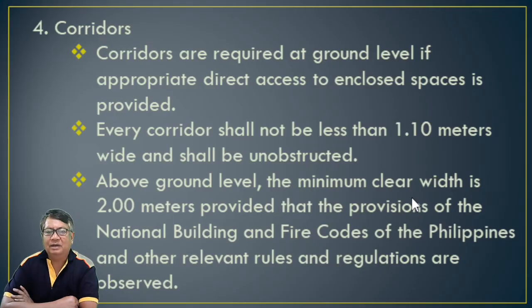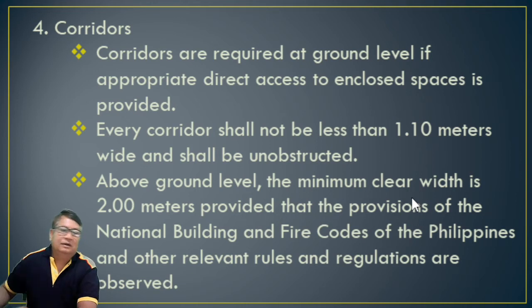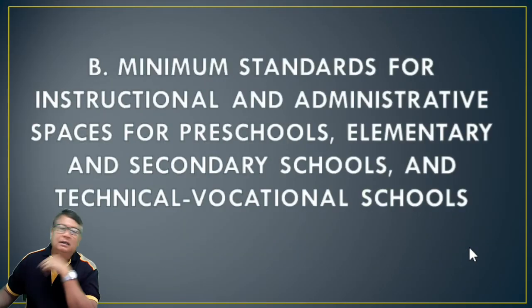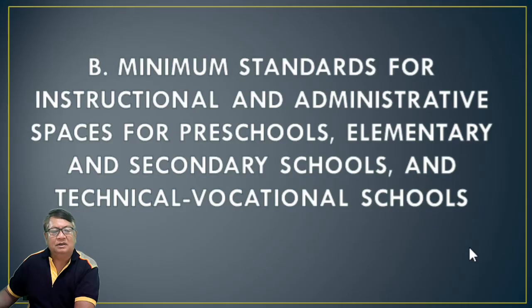Above ground level, the minimum clear width is 2.0 meters, provided that the provisions of the National Building and Fire Codes of the Philippines and other relevant rules and regulations are observed. Exit doors and other alleys and corridors should always be open and available for any passersby.